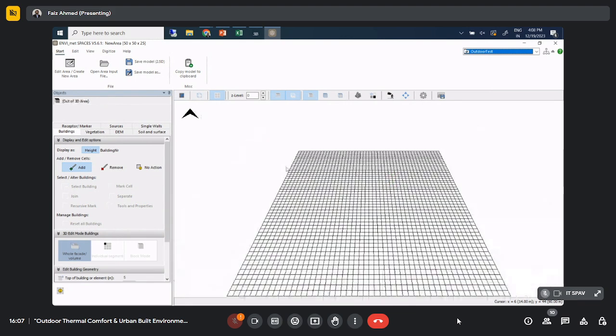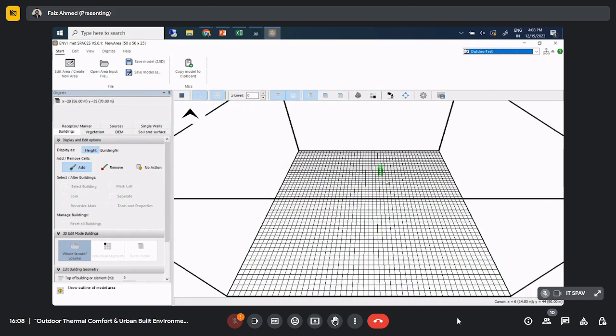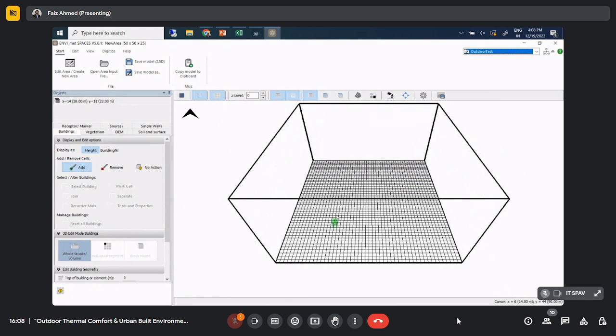This is for 3D visualization, and this is the entire frame in which the entire model will be made, and we can visualize this. And the only point to be remembered is we should not touch the boundaries. Theoretically, it should not touch the boundaries, to avoid errors. Otherwise, we'll have errors in the results.